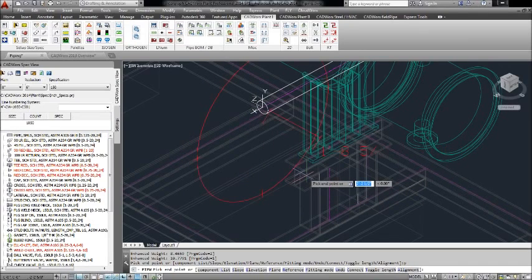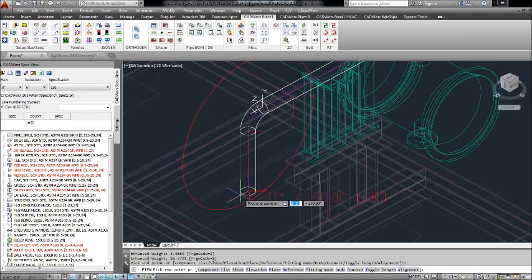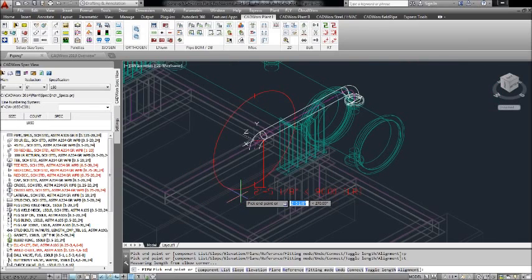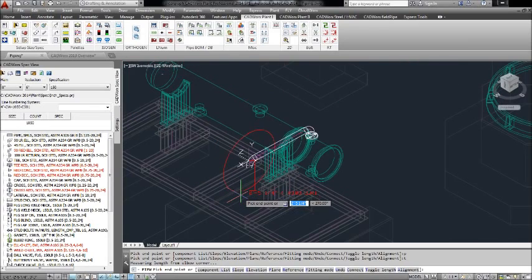I've got my dynamic input turned on, so it's being blocked a little bit, but when I pull over this direction, you can see I'm getting full dimensions there. And currently, it's dimensioning to the weld for my next spool piece. But if we're routing from centerline dimensions per a sketch, we could certainly toggle that by hitting T and Enter. And now we're running by centerline routing.